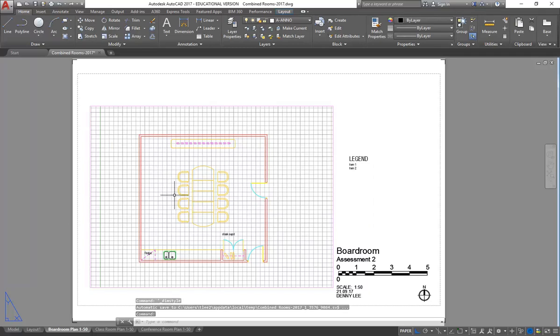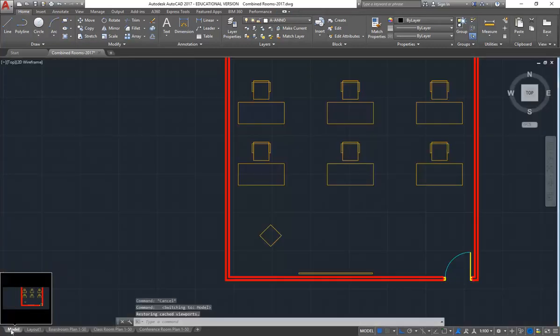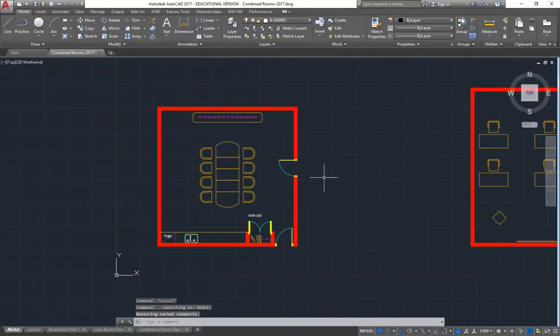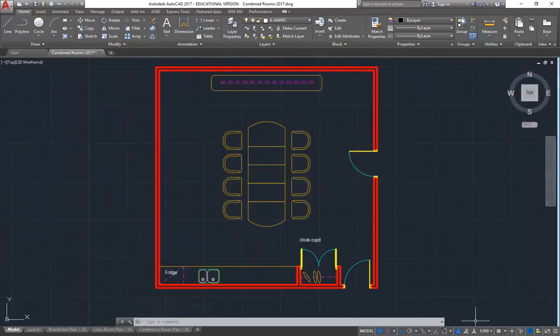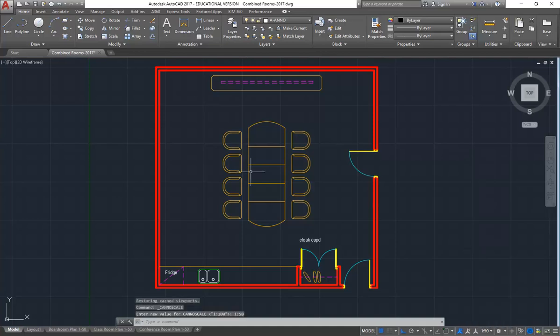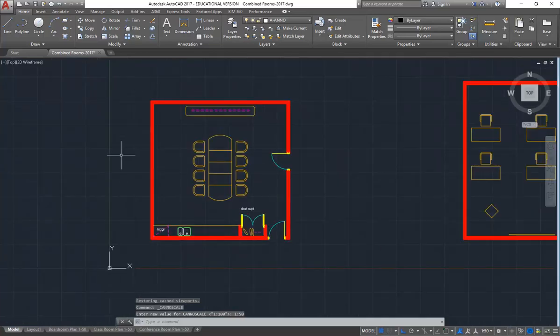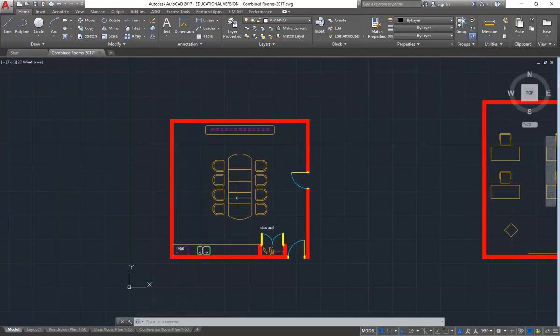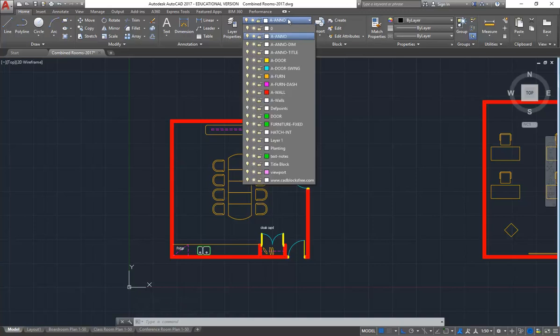And then you can see I'm on a layout, so I'm going to go back to the Model tab, bottom left, and then go to my first plan, and really important, make sure that the scale in the bottom right there is set to 1 to 50 before I draw my dimension. And then I'm going to change to the layer that I've made for my dimensions. So I've already made a layer called Annotative.